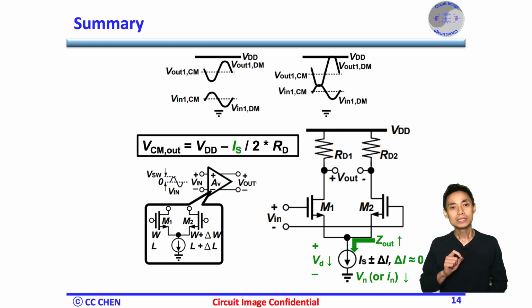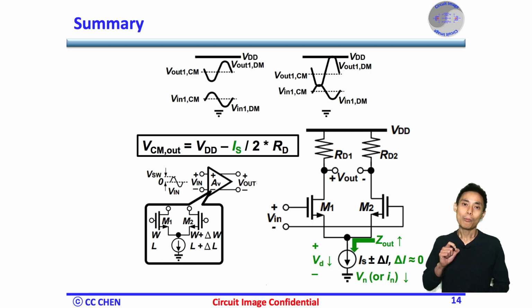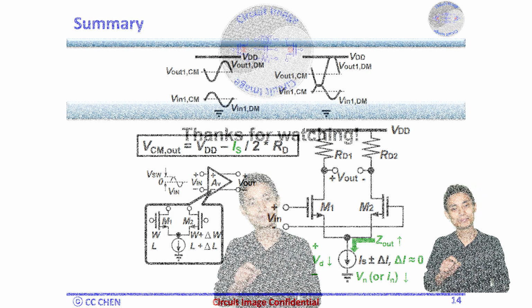Again, please be advised that the differential amplifier is just a case study of why you need the current source, since the current mode logic CML amplifier is the most extensively used analog block. The other circuitry would also require a current source for robust biasing, and the corresponding requirements would be almost the same: a better accuracy, a less headroom consumption, a low noise, and a higher output impedance if possible.